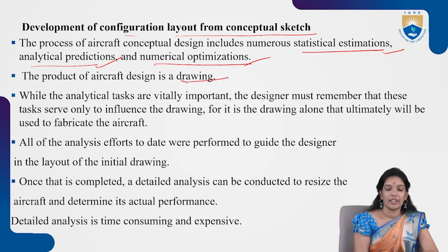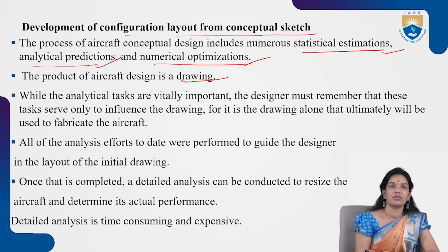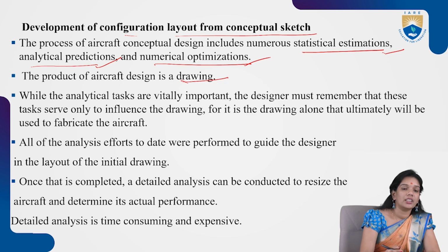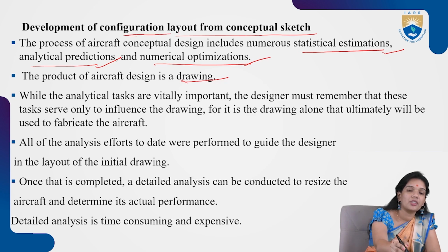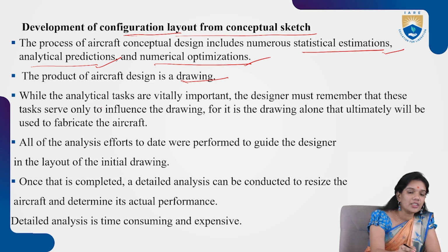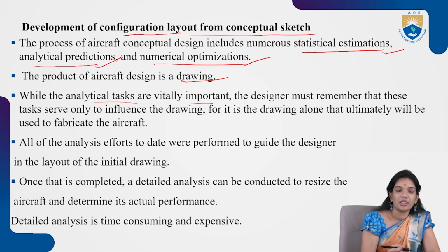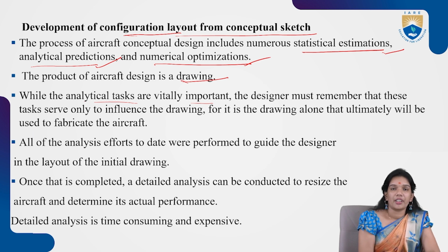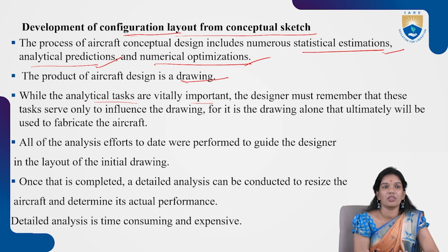I want to know exactly where all the different components are going to be placed, how all of them are going to be accommodated in that particular huge aircraft, right? So at the end, it is going to be developing your layout, or development of a configuration layout, right? While all these analytical tasks are important, how much fuel has to be consumed with respect to that particular range, or when you're trying to climb and accelerate, or when you have a loiter for 30 minutes or 20 minutes, or if there is a weapon drop, right? All these estimations need to be done.